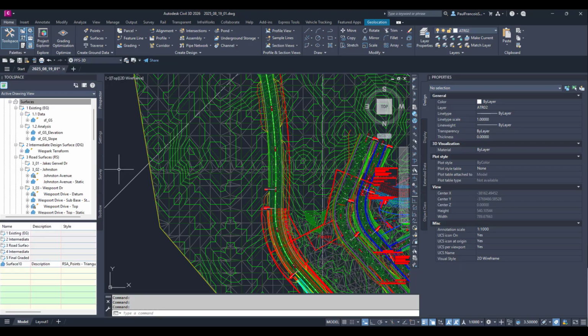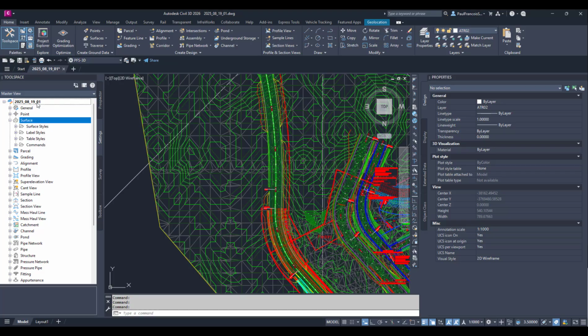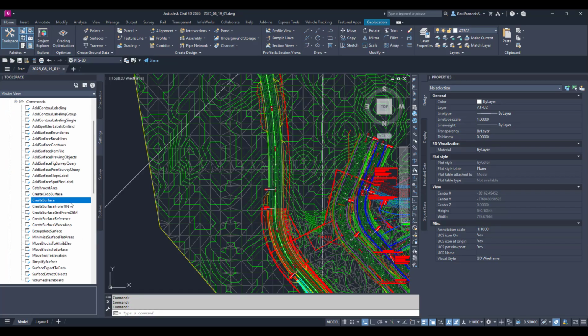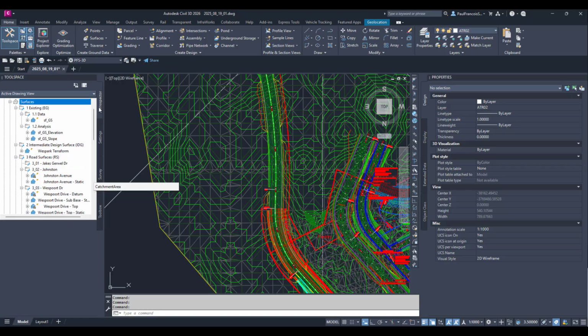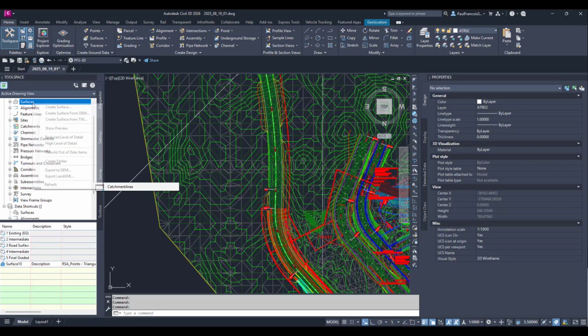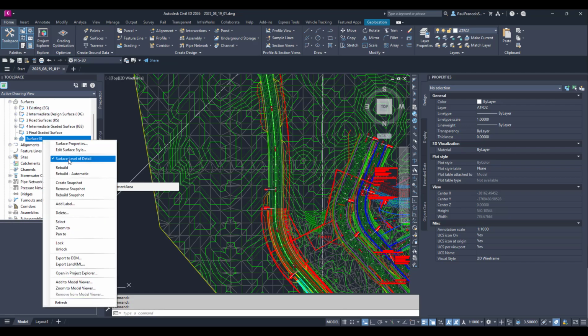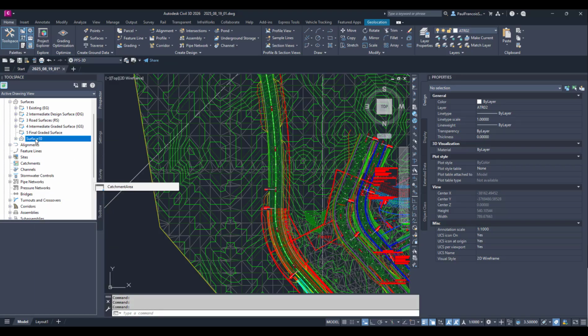There we go. Alright, so you can see there's quite a few things going on. One is there's nothing on the drawing level for the defaults for the surfaces. On the object level, we've got settings. On the command level, with create surface, we've got settings. And then on the prospector, we've got the ability to set those settings, reduced level of detail, high level of detail on the surfaces. And we've got an override on individual surfaces by accepting to have the surface level of detail or not.